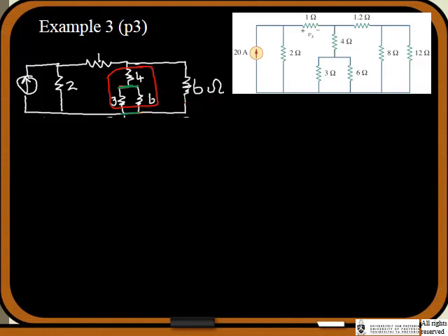And now we've solved for the voltage across I1, but what we found in the process is the current that is flowing through I1. So let's use red. We know that the current that's flowing through here is 6.6 repeating amps. That's flowing through that circuit.